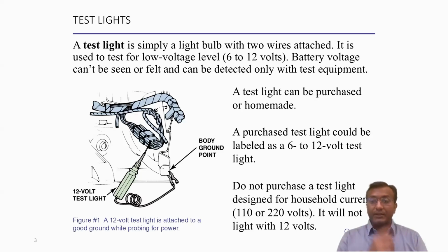So our first piece of equipment is the test light. It is used for finding out whether supply is present in a particular line. These test lights are simple and effective. A bulb with two wires is attached, commonly used to detect voltage in low voltage circuits like in cars. For instance, when troubleshooting a dead circuit in a car, a test light connected to ground and probing each circuit point can quickly confirm where the voltage is present and where it is not.